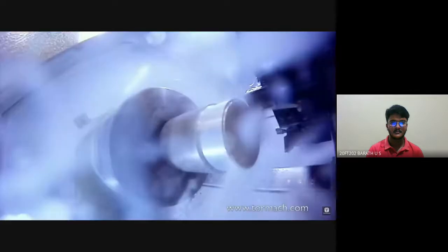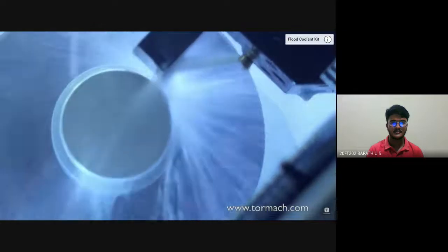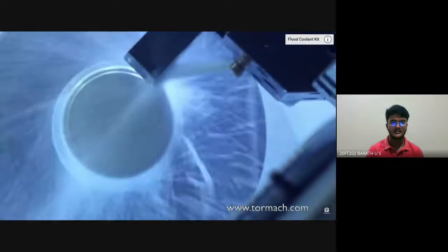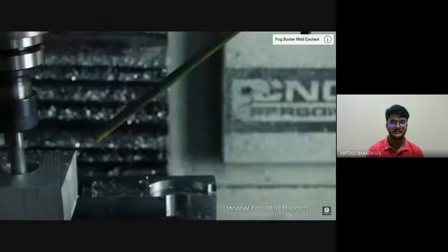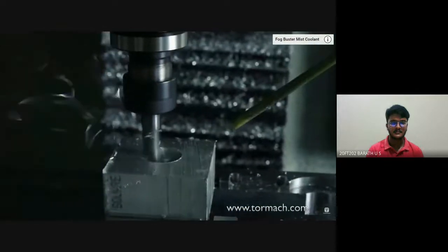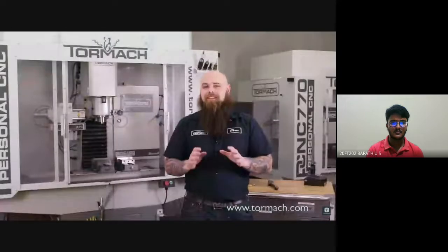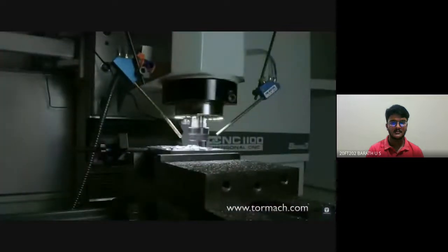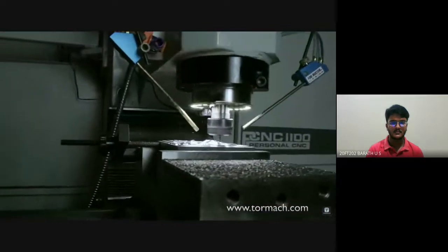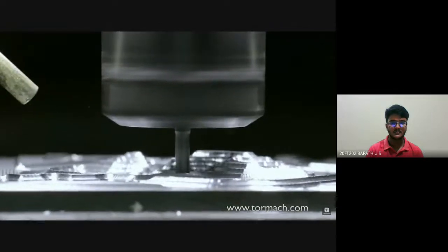What you're cutting and how you're cutting it will determine how you use coolant and the method of delivery. Flood coolant literally floods, sometimes blasts, your part with this liquid. This helps get chips out of the way while also lubricating and cooling your tool. Depending on what you're cutting, the mess is typically worth it. Mist coolant is another option. It uses a combination of air and coolant to deliver a saturated mist at your cutter. This helps clear chips and lubricates, but it doesn't do much cooling. And then there's boring old air. No lubrication and only a little cooling, but it does clear those chips.